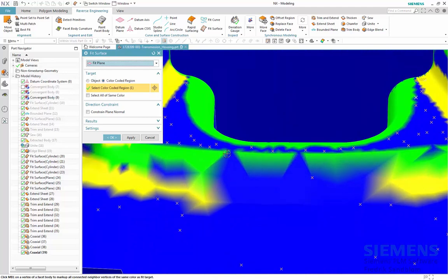When selecting the small planar recession color-coded area representing the top face of the recession, we realize that the selection becomes wrong. This is probably because the planar face is not properly limited by a different color. We therefore, in this case, manually recolor areas that are not quite correctly participating in the color-coded boundary to be planar.